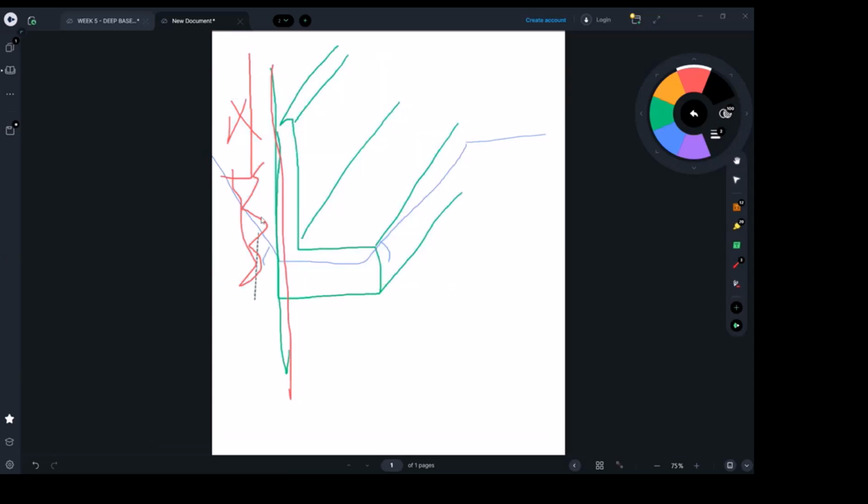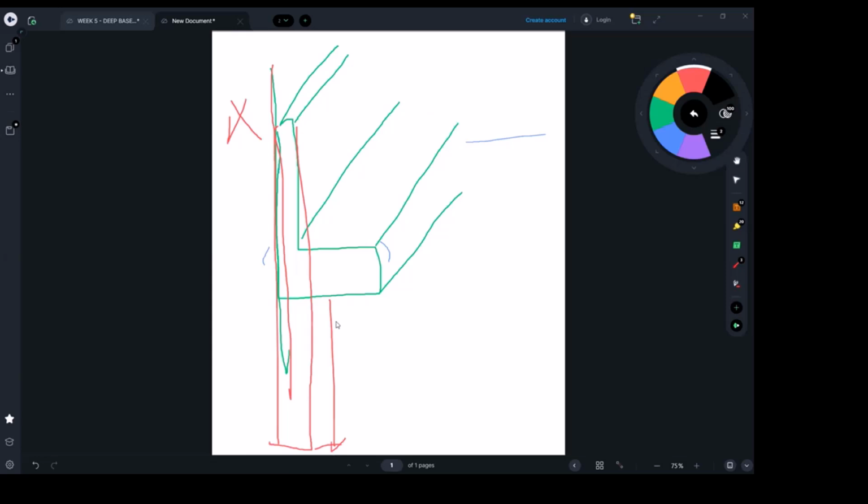So now why does it work with a retention system of whichever type, secant or contiguous or soldier piles? Because the pile we're going to take all the way embedded into the ground. And as I said, if we're not using anchors, this will be 2 times X. X is the basement height if there are no anchors. And usually anchors will slow the project and will cost more. So yes, it's better not to use them.